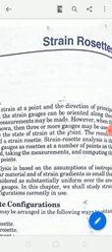So how can we define strain rosettes? A strain rosette can be defined as strain gauges arranged in a systematic way, or we can call the strain gauge configuration a strain rosette. If you want to know the strain at a point, then you have to orient gauges along that point.